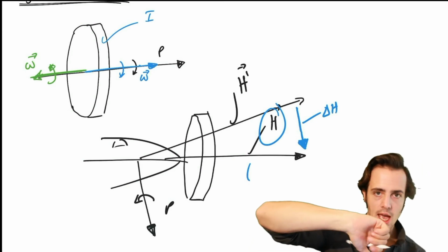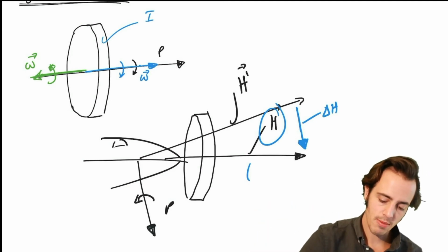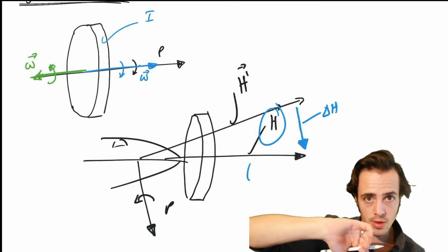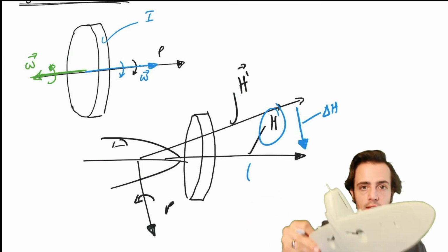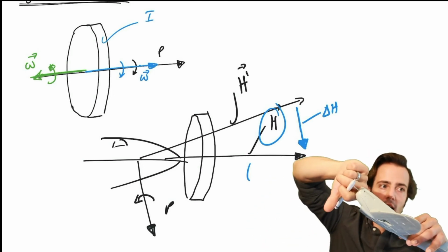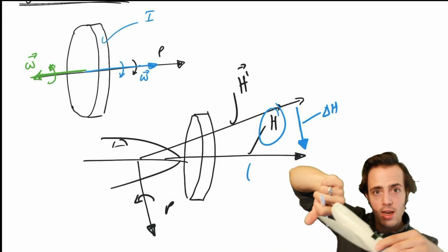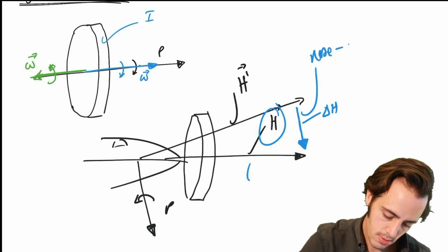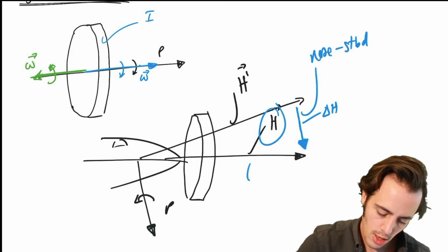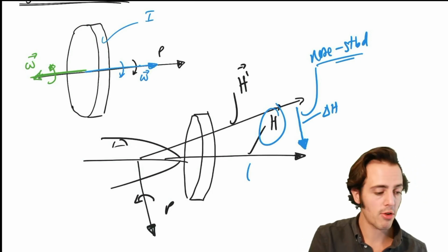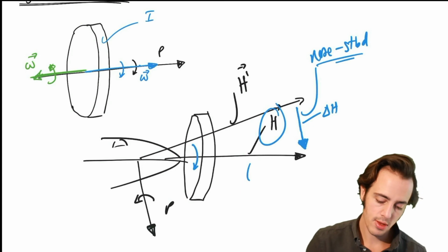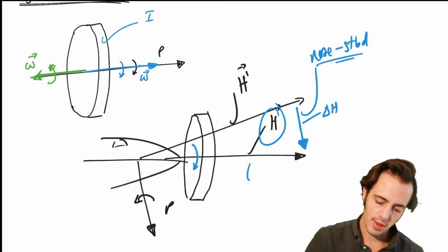Now this is then an angular momentum vector, which I've drawn in blue. It's pointing downwards in this new aircraft rotating axis. So here I've got my downwards vector. This is then a nose starboard. Okay, and this is for the case where I've got an aircraft with a propeller that is clockwise when viewed from the pilot's sense.